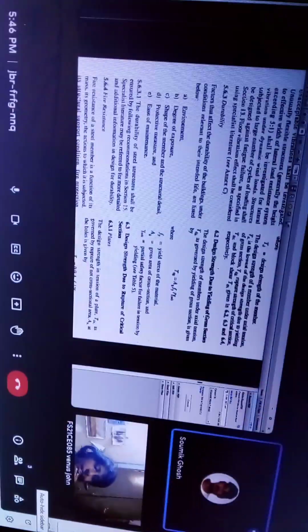And here this is the design part. When we already know that in a truss there are, suppose, 12 members, and 5 of them are tension members and 7 are compression members, we know which members are tension and which are compression. We also know from that analysis how much load is coming on each member. So to resist that particular load, we will design that member.